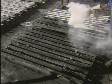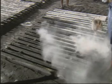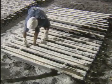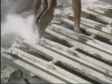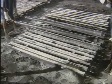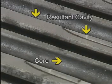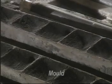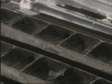Soapstone powder is now sprinkled on the inner surfaces of the cope and the drag. The core is placed into the drag. The resultant cavity in the mold corresponds to the thickness of the pipe. The cope is now placed on top. The mold is now ready for pouring.